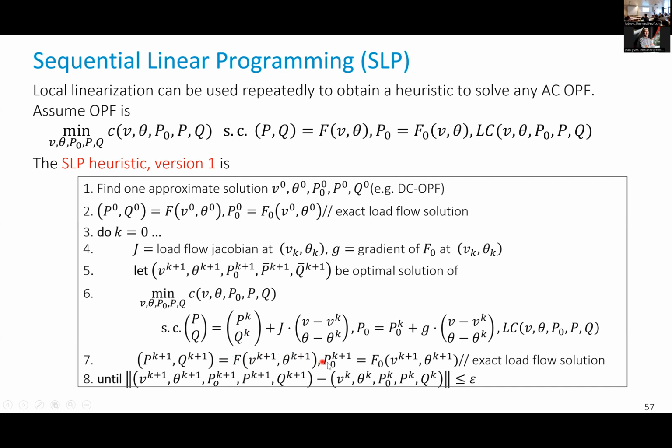So what I can do is solve them exactly. That is not a load flow, because here I take the v and the theta that are the solution of this optimal problem here. So the solution is v, theta, and the PQ component, I call them with a bar here. I will throw them away. They will not be used. I will replace the P bar, Q bar, which are not the exact power, they are satisfying this linearization, I replace them by the true values here.